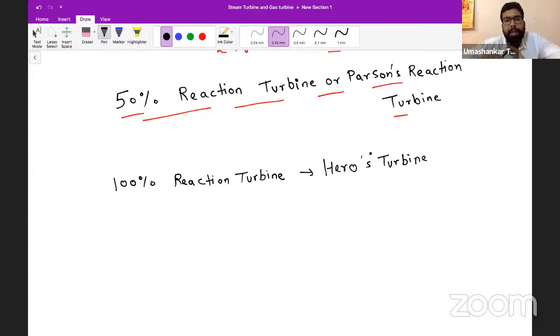There is no blade in it, but there is high axial force happening in it. Steam flows from a nozzle and strikes some rotating part, and it gets rotated. So it is a very basic design. In history, this was the first ever working steam turbine.